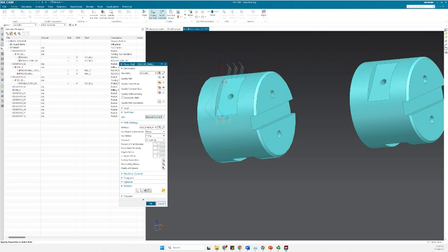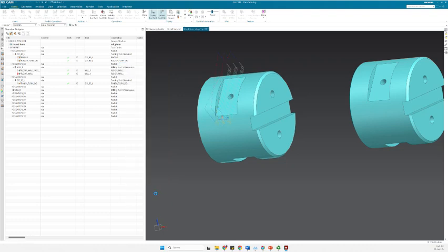Otherwise, either we're going to have this sharp corner rounded, which is obviously a defect, or we're going to have a very low surface quality. But by just defining the tool axis correctly, these two problems are solved. All right, let's generate the tool path and verify that.